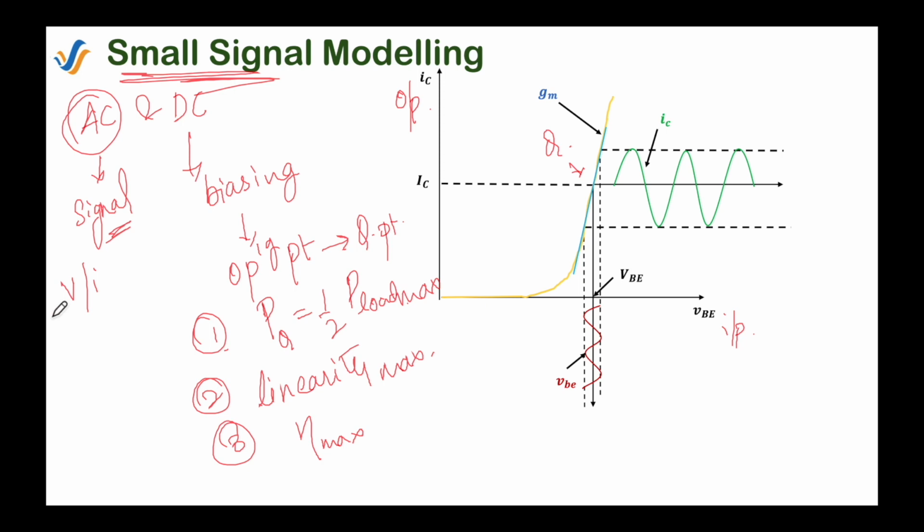Definitely we are comparing with something. So with whom are we comparing that this signal is small or not? Are we comparing with the DC supplies which are used for biasing in the electronic circuit? No. We are not comparing with the DC supplies. A signal is called a small signal when the value of its amplitude is such that it can make the circuit operate linearly. So whether a signal is small or not is again defined by the input-output characteristic of the circuit.